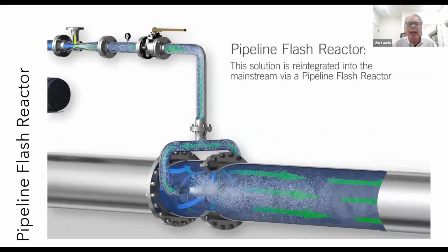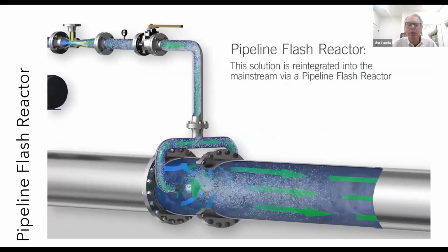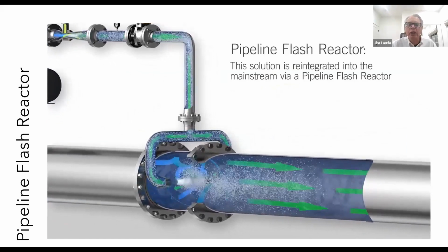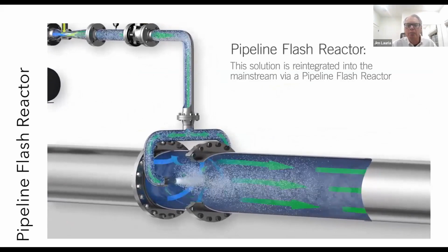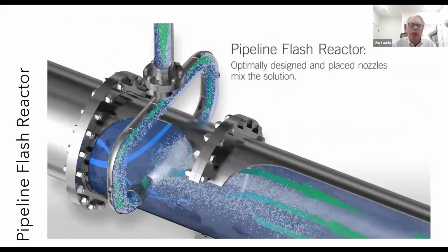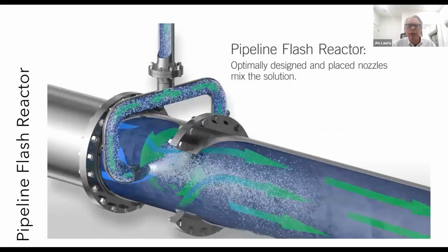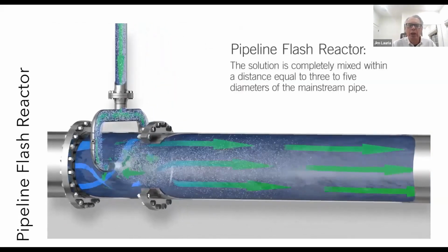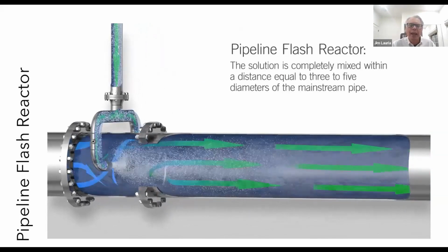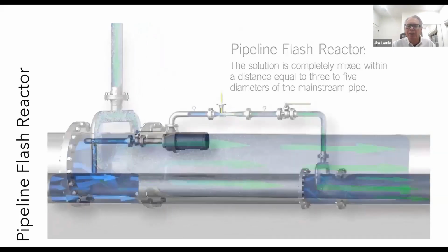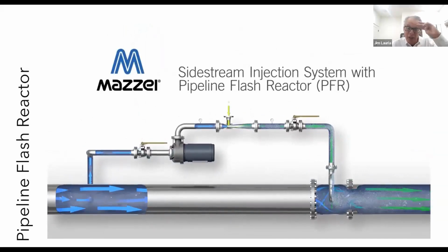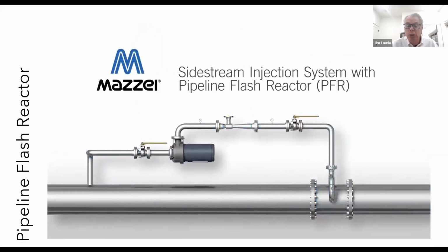And then the mixed gas that you're pulling in, now you're mixing that back in, the 10% high concentration gas-liquid flow back in with these specially designed nozzles that mix in this water-gas mix so that you get this homogeneous mix and you get as much gas dissolved in as possible. Typically about 95% mass transfer for the gas-liquid, which is pretty high compared to a lot of the other technologies.